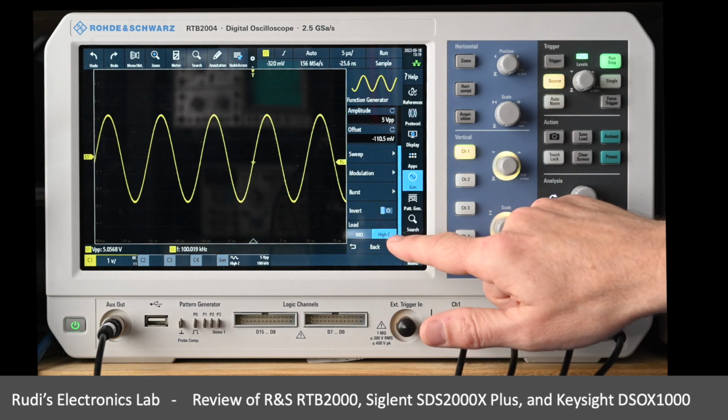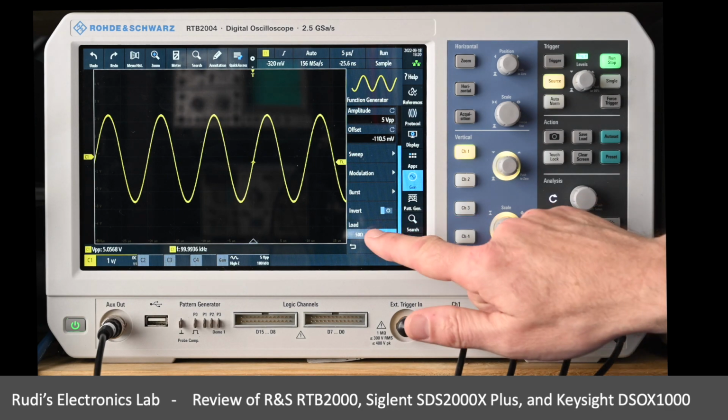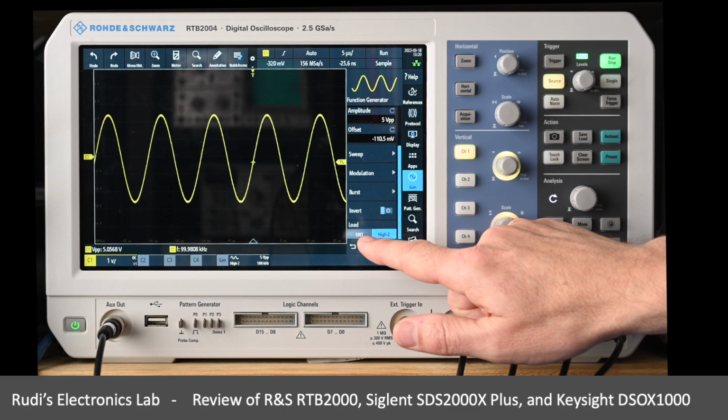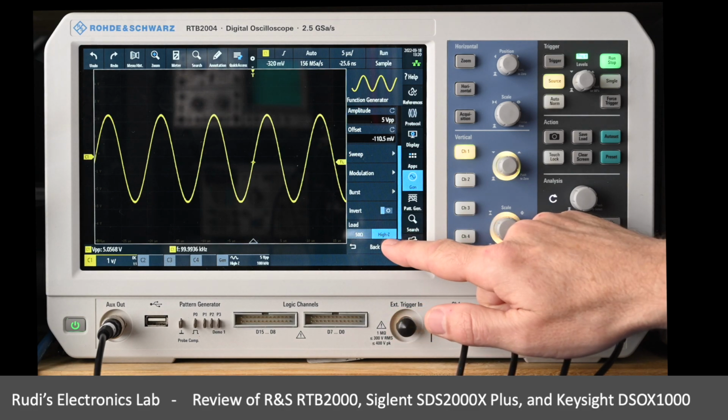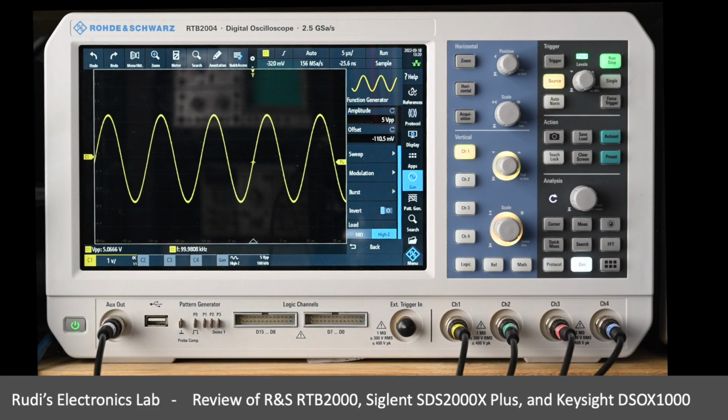Here we got the load, which can be specified as 50 ohms and a high load, high Z. All the three devices here have a similar functionality, and it's rather common on standalone signal generators as well. But before you get too excited, this is actually not something about the real output impedance of the signal generator. The signal generator always has an output impedance of 50 ohms, whatever setting you choose here.